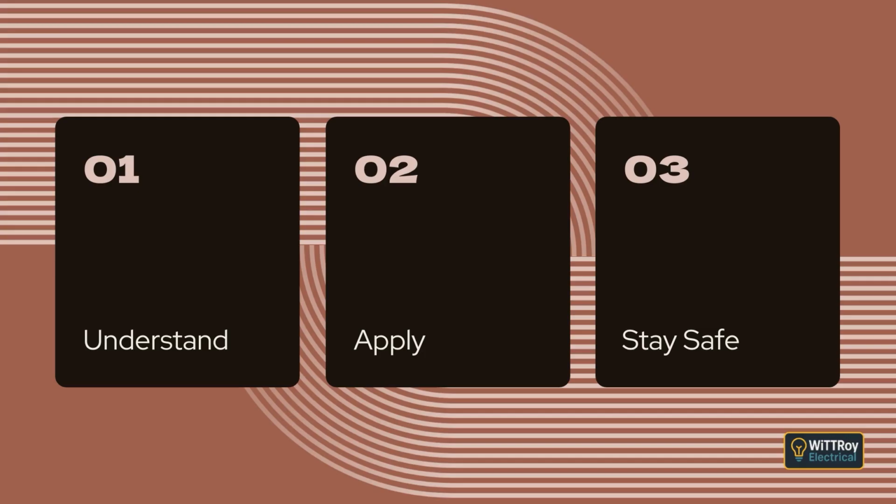Clause 2.3.4.5 Appliances and accessories. Many appliances and accessories require their own isolation or switching. These include water heaters, ovens, motors, room heaters, air conditioners, and safety services. The detailed requirements are found in sections 4 and 7. The main ideas: whenever an appliance might need service or might create danger if accidentally energized, it must have a way to isolate it safely and locally.